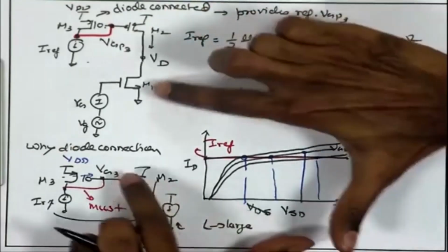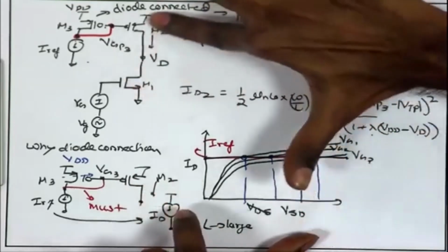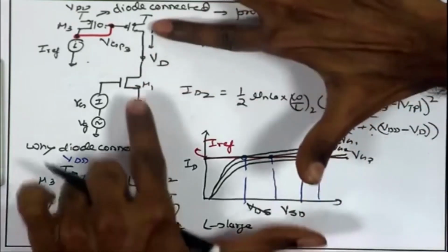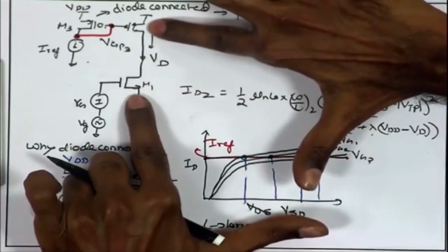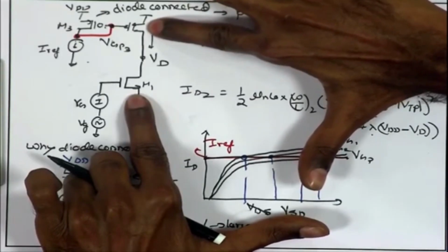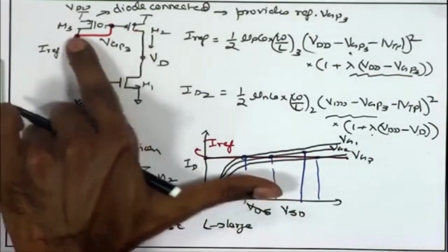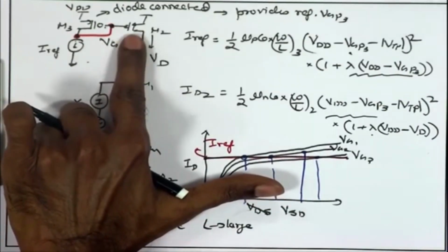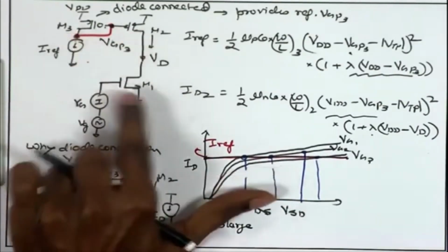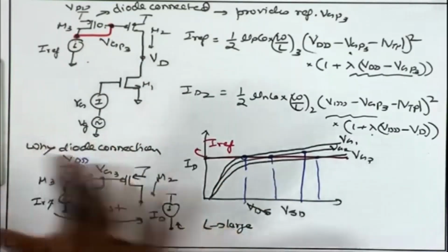But the key point is that M1 and M2 are two different kinds of transistor, PMOS and NMOS. Their parameters, their threshold voltages cannot be very well matched, but in an integrated circuit environment, threshold voltages, even effectively the lambda of two PMOS transistors or two NMOS transistors, can be pretty well matched. And there comes the concept of layout.